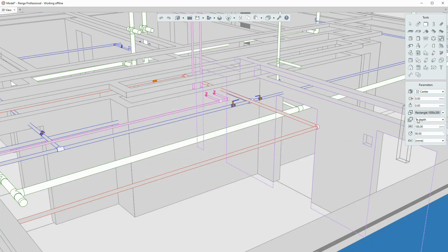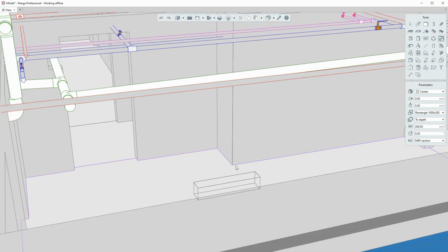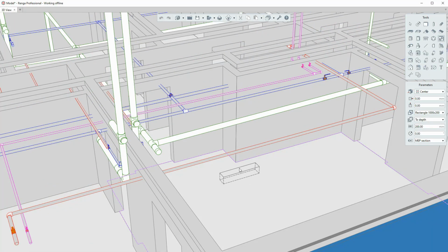Hole extent: select one of the following options. Hole depth, hole rotation angle, and mark. The mark appears in the schedules and is necessary for insertion into the drawing. Parameters may be modified both when constructing the hole and when editing. Press Enter to fix the parameter values. Then, specify the insertion point on the wall, beam, column, floor, isolated foundation or wall foundation face using snaps.